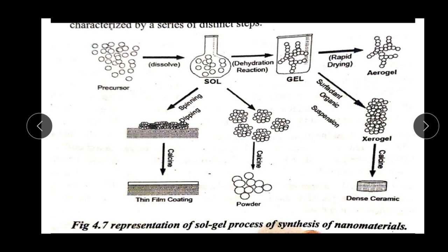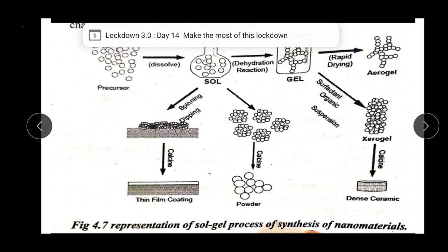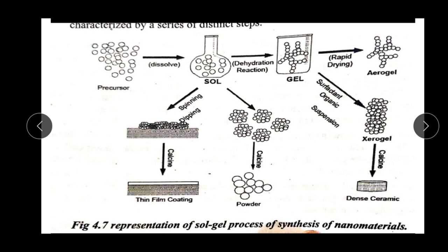dehydration, during which surface-bound groups are removed. These may stabilize the gel against rehydration. This is normally achieved by calcining the monolith at a temperature up to 800 degrees Celsius.